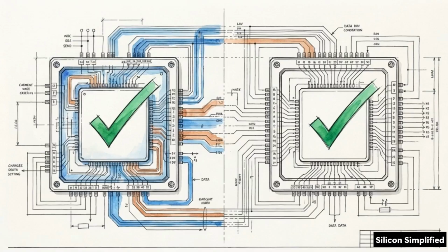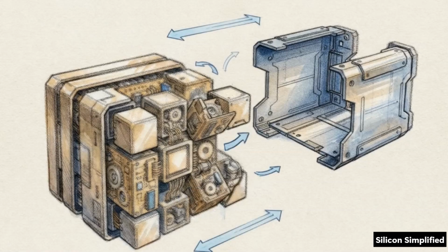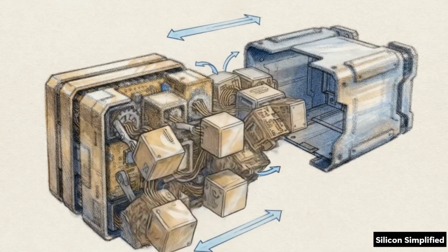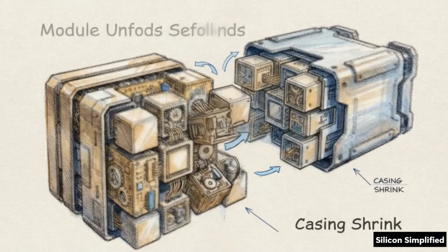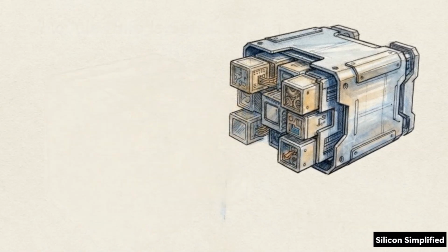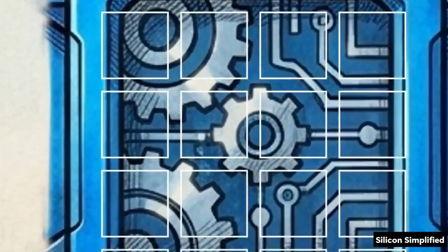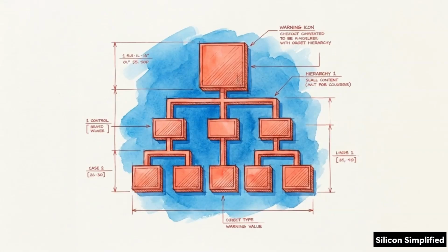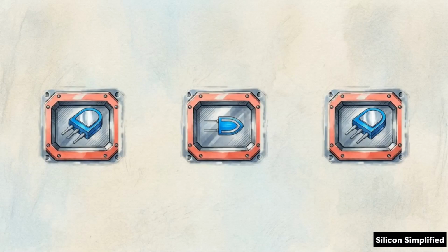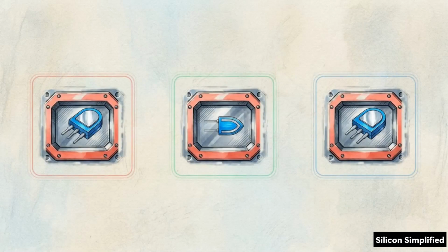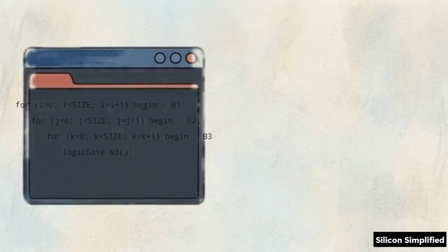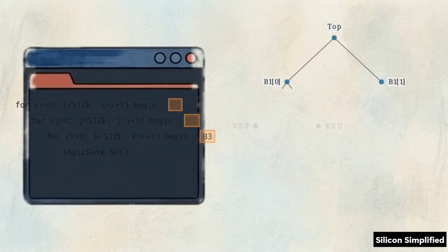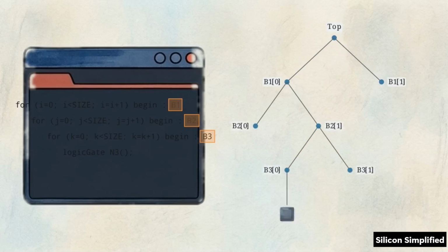System architectures frequently require multi-dimensional arrays, which demand loops nested inside other loops. This introduces a strict rule of hierarchy. Every instantiation of a generate block is treated by the compiler as a completely separate scope. Writing nested B1, B2, and B3 loops makes the compiler build a specific hardware tree. Each iteration creates a deeper branch. Naming each block declares an organized instance array, creating an exact address for every single gate, from B10 down to N3.